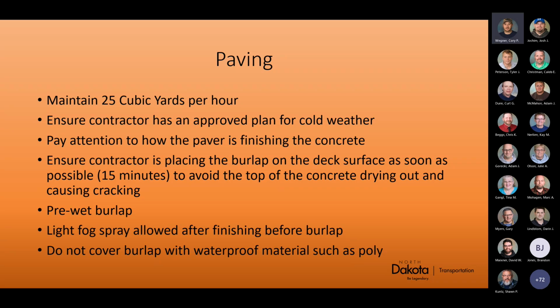And we don't want that. Then you end up with some issues. So only allow a mist. Most contractors, I think, use a pressure washer to give a mist over it. And then don't cover the burlap with waterproof material. That's right in the spec book. So just don't allow it. We've had contractors try it.